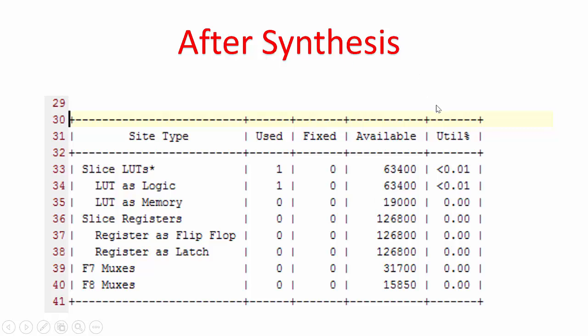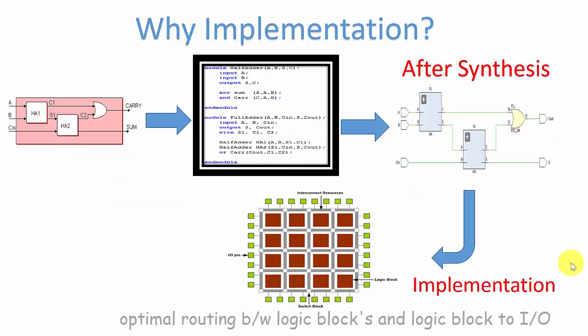Our logic will be converted into RTL, register transfer level, based on the elements available in CLBs. For your logic, how many lookup tables are utilized, how many memory elements are used, and how many registers and muxes are used. This report will be provided with synthesis.